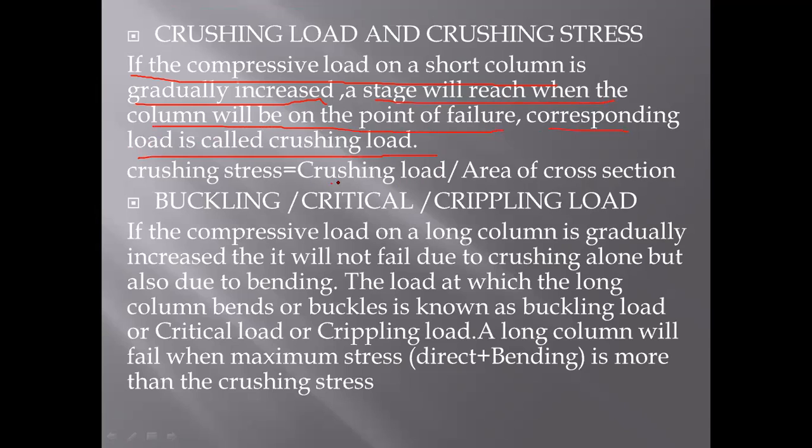And crushing load upon the area of cross section is called the crushing stress. Then what is buckling and crippling? If the compressive load on a long column is gradually increased, then it will not fail due to crushing alone. If the column is long and you are applying a compressive load, then the column will not fail due to only crushing load, but also due to bending.